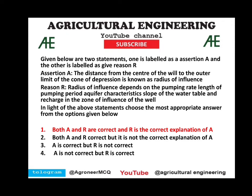This one is correct. Radius of influence depends on the pumping rate, length of pumping period, aquifer characteristics, slope of the water table and recharge in the zone of influence of the well. So this one is also correct. So both statements A and R are correct, and R is the correct explanation for A.